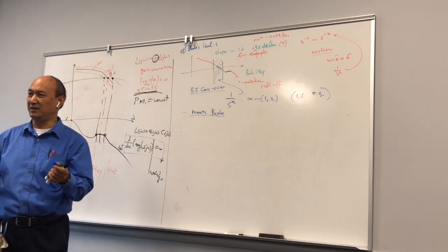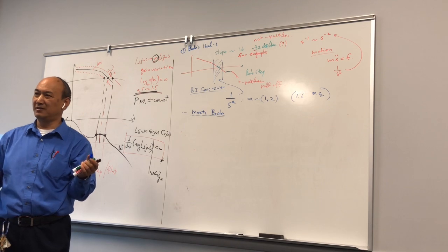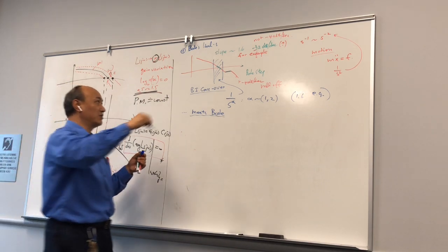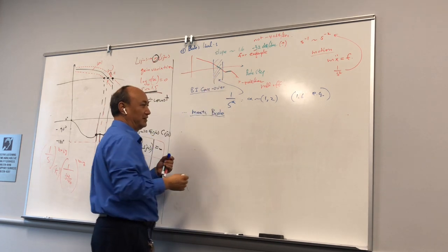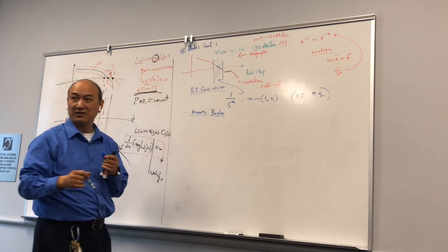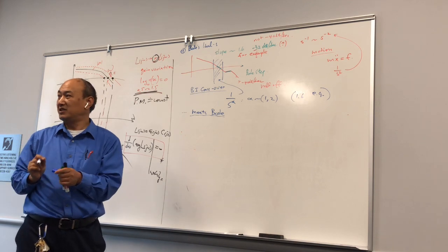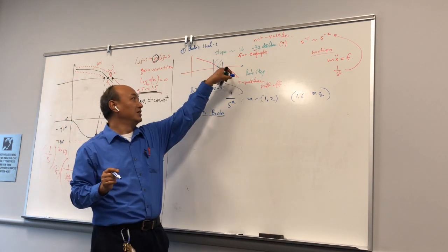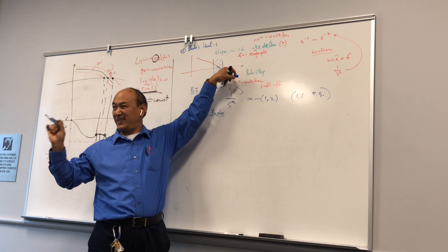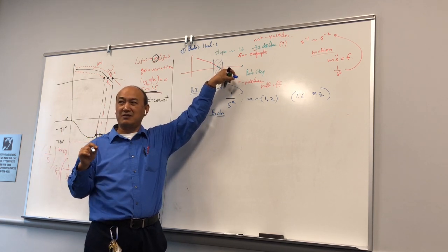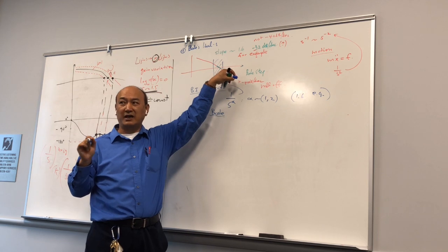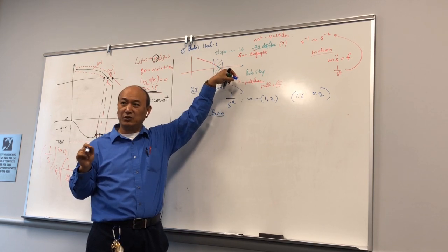So in the end product, when you have a gain crossover, your phase is flat. But how you achieve the phase flatness requires a mechanism that is not seen carefully in any textbook, except Boris Luria and his book. He wrote a book called Feedback Maximization.